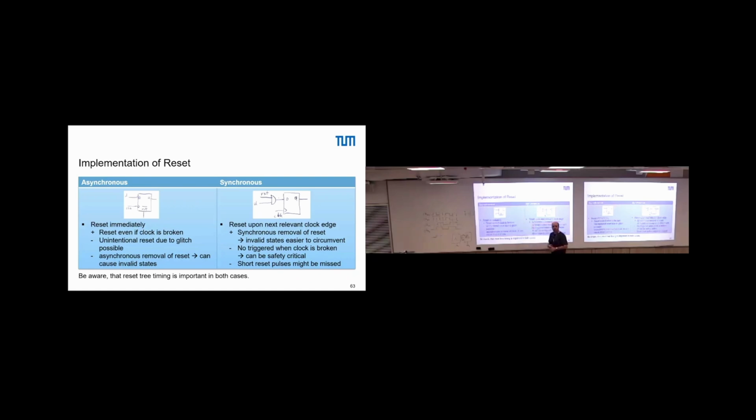This is nice because I do not depend on any clock. I have not any delay. If I want to run time critical into a reset state, this helps me. Yes? So this one is the usual case you implement in an ASIC, every individual flip-flop. This one is the case you implement usually in an FPGA, every flip-flop. The usual, not the necessary.